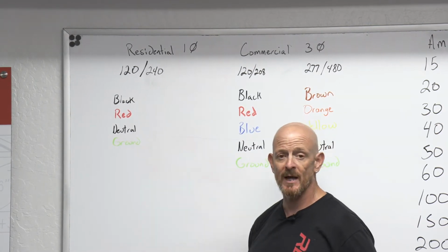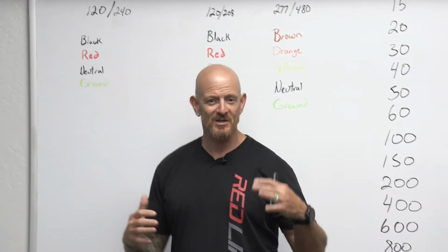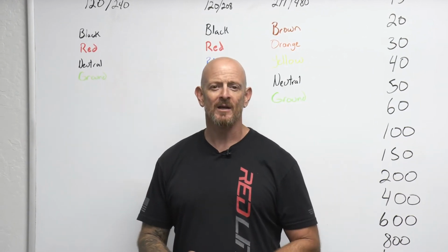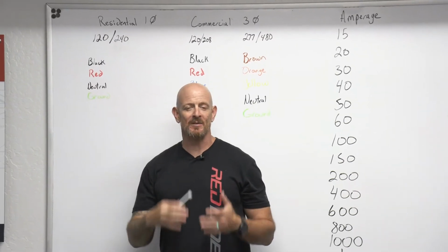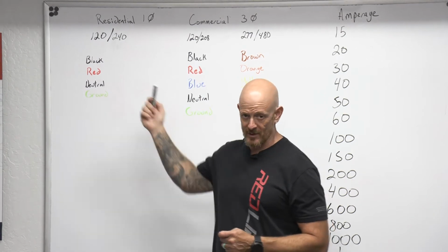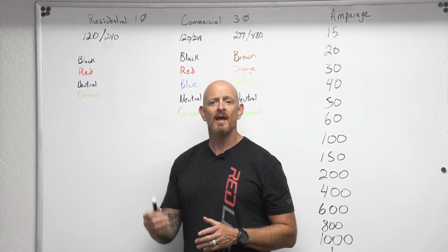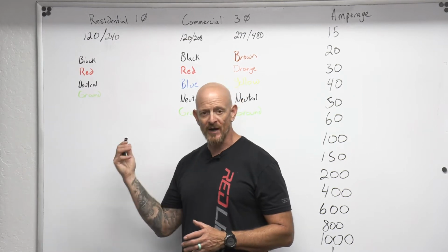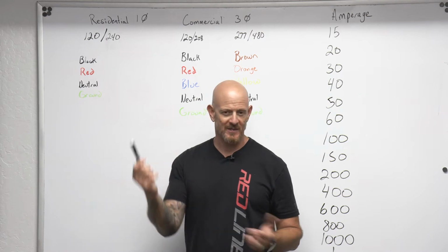So when somebody asks you for a 210 outlet, there's really no such thing as a 210 outlet. These are the systems that you run into in America. When you hear somebody say that they need a 210 volt outlet, we're going to round that, and they're going to get 240 volts. So if the equipment says 210 and it's running at 10 amps, we're going to provide it with 240 volts. Well, it's going to run at 8.75 amps because that's just math.